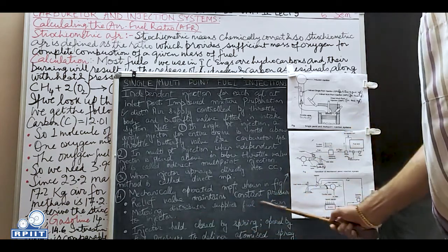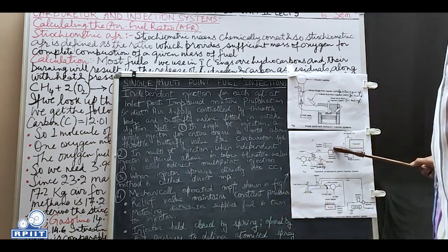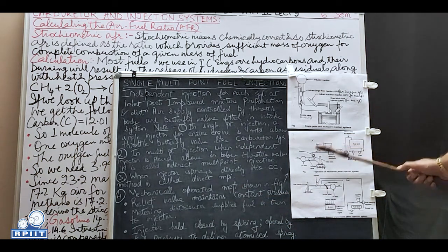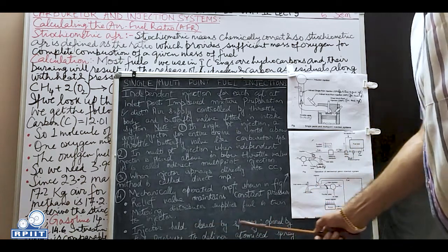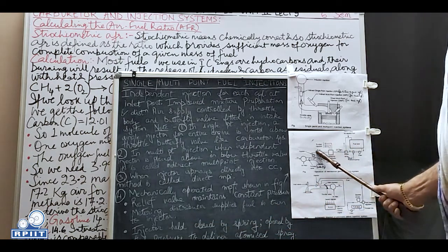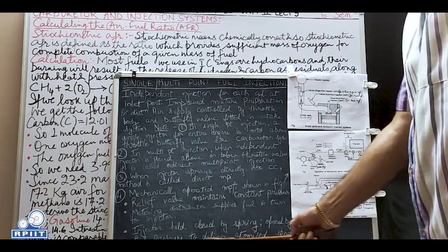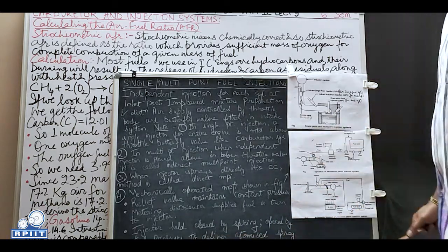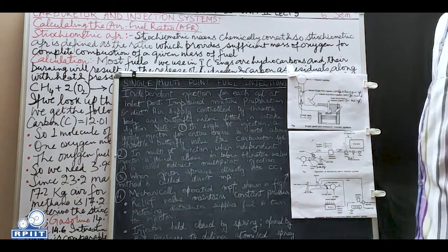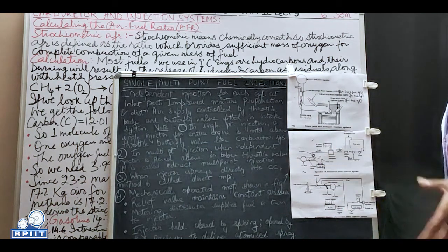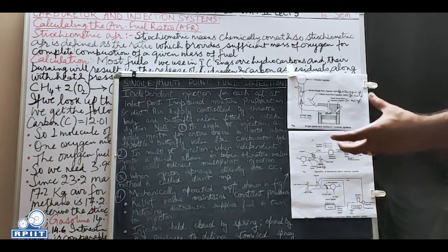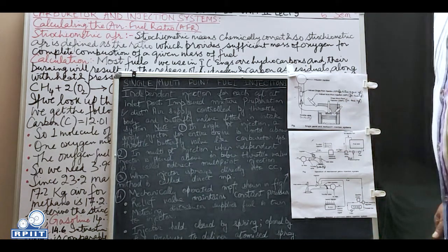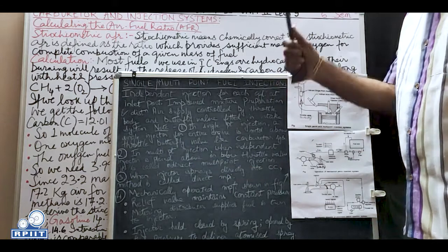The metering distributor supplies fuel in turn to the injectors. The timing is controlled as per the timing of the engine cylinders. The injector is held closed by a spring and opened by fuel pressure to deliver an atomized spray. The atomized spray then mixes with the air and gives the air-fuel mixture, the petrol-air mixture inside the combustion chamber, which further powers the engine and the vehicle.